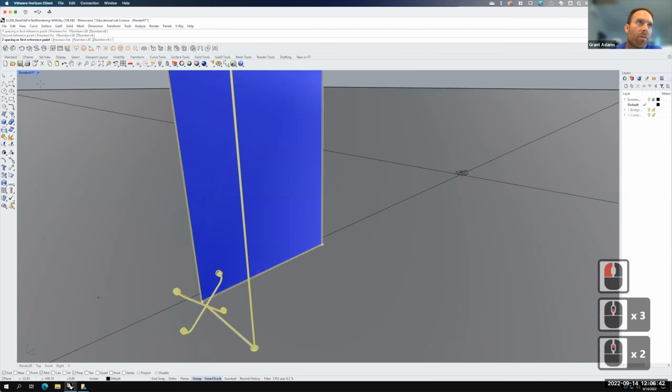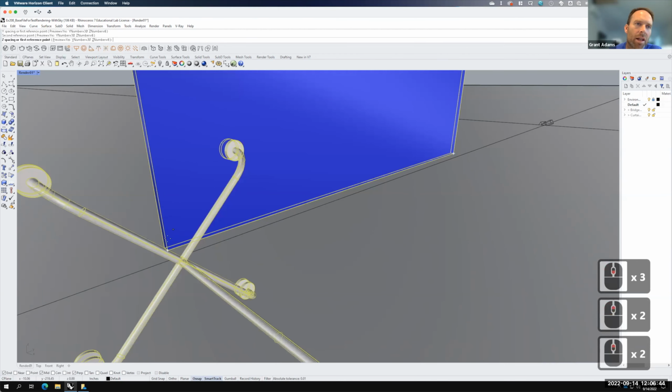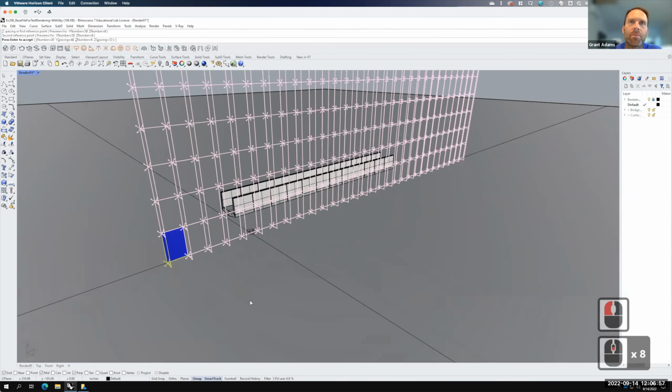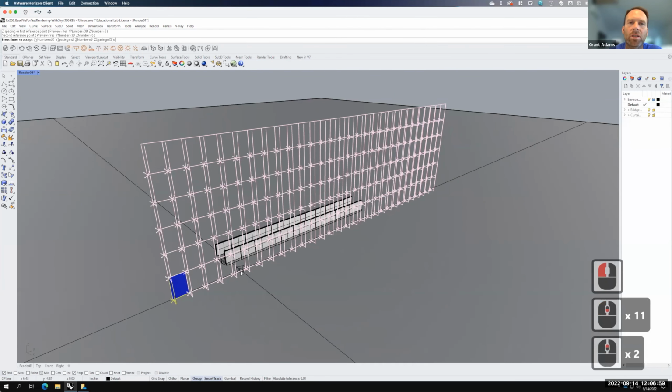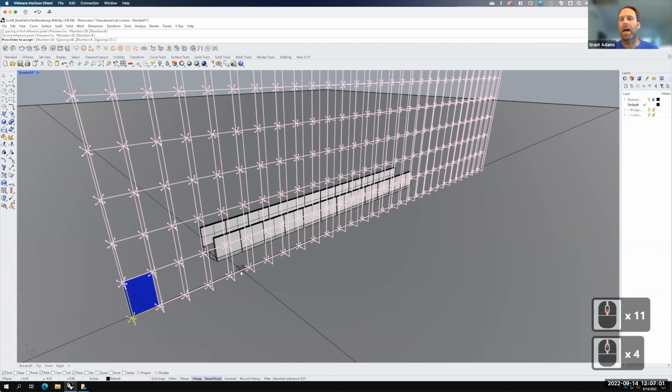Let me do it for the Z spacing. It's going to be the vertical glass. So we'll go again from that point right there, and we'll go up in that direction to right there. And now in this pink, it gives us a preview of what it looks like. So we've just built a huge wall out of one piece because of how we created the geometry originally. That's a great strategy. Let's go ahead and commit to it, and I'll hit enter.